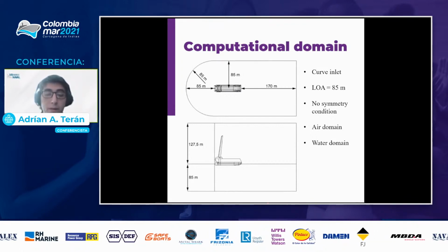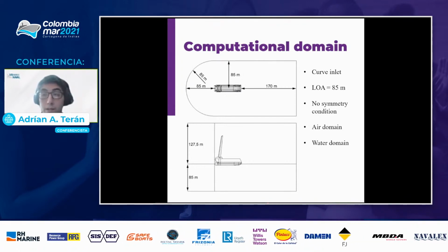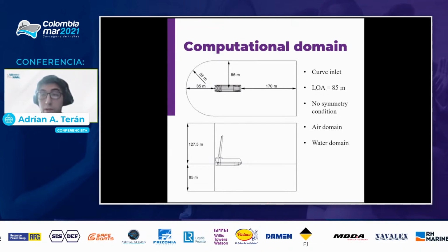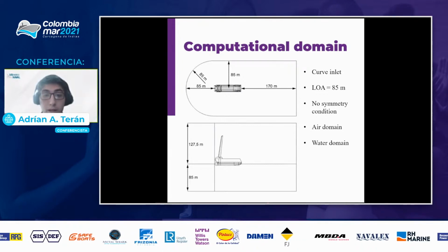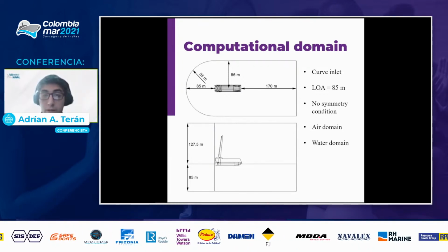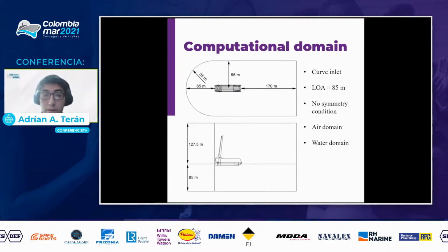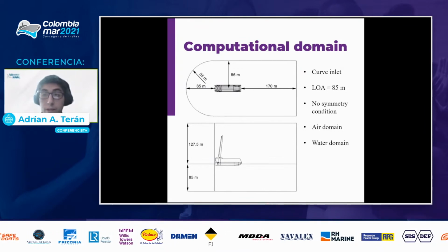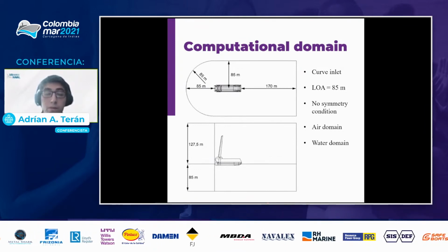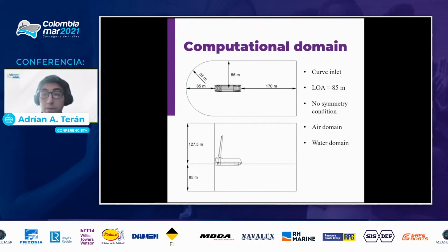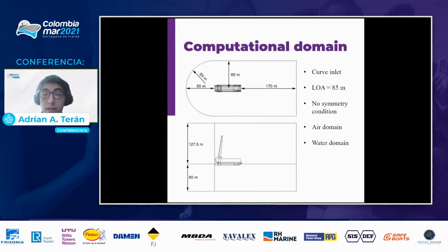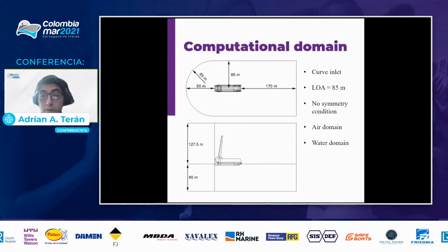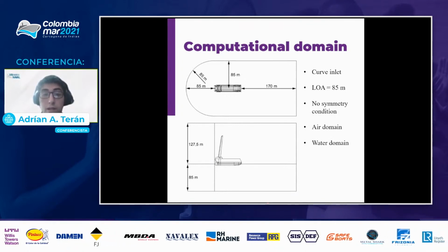Now, in this analysis, what we normally do is, instead of the ship moving at a certain speed in a given space, such as a towing tank channel, we can create a working domain, which is going to be called a computational domain, where the whole of the ship is going to be placed at a prudent distance from the bow, a water inlet where the vessel is operating.